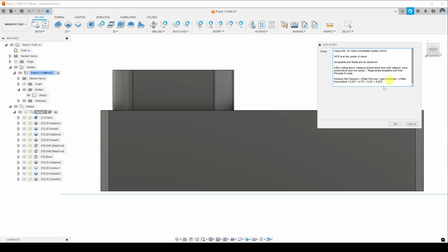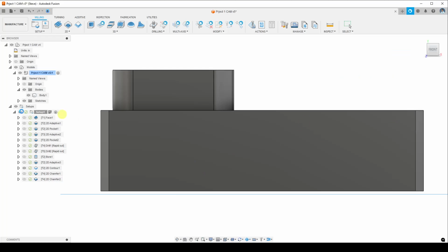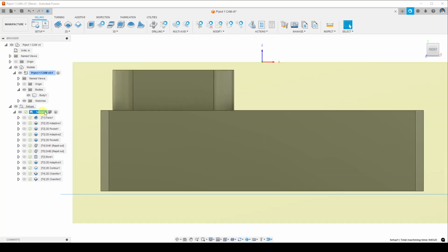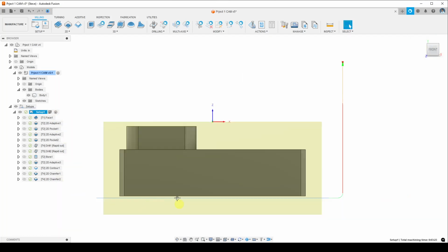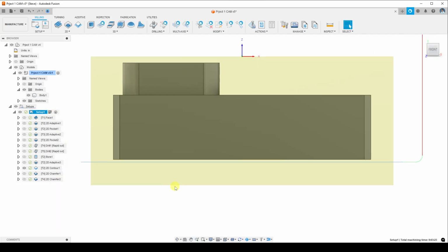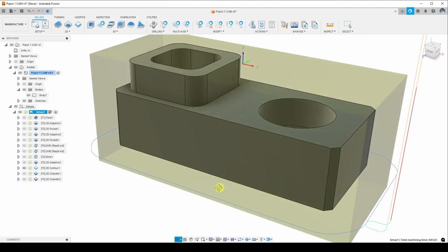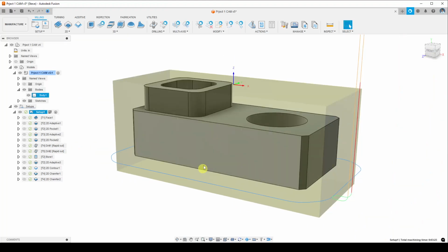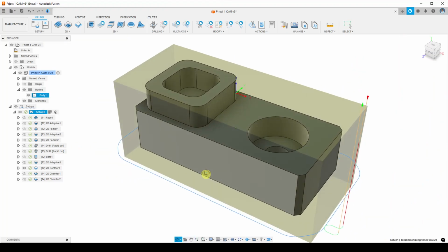If it was exactly 0.82 inches, you might still actually hit the vise because there's air all over the place. So you want it more than that. How much more? Well, it depends on what you're comfortable with and your experience level. But you have to balance that with the amount of stock that you have clamped in the vise, which in most cases is a minimum of 1/8 of an inch. So yeah, it's a balance. You have to find the way, but knowing that 0.82 number is key, and you're going to have to know that for every part that you machine.